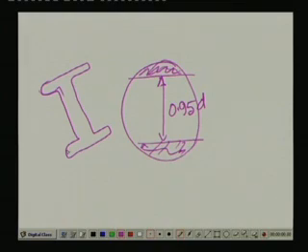Similarly, if you are having a rotating I section or any other section for that matter, you can have an equivalent diameter, or what I have just called an effective diameter, which can be calculated, and you can find the references in the design data book. I am not explaining each and everything, but just giving you some concepts and examples for a few situations.